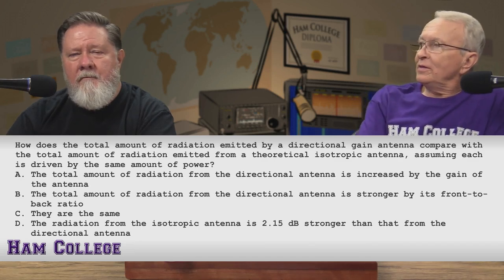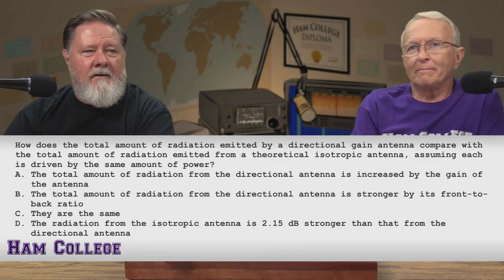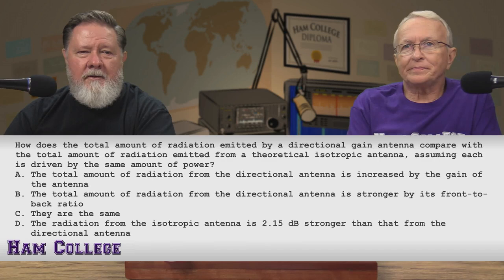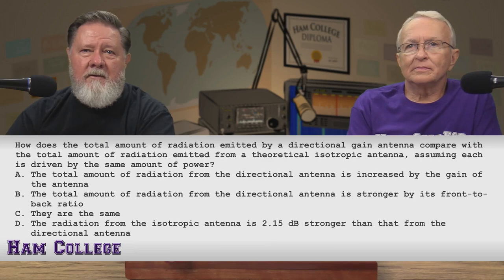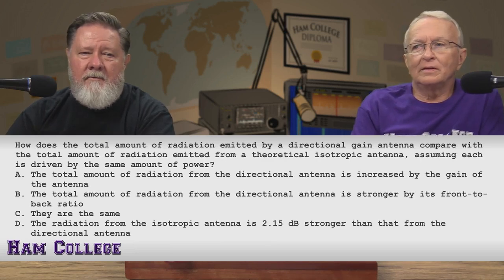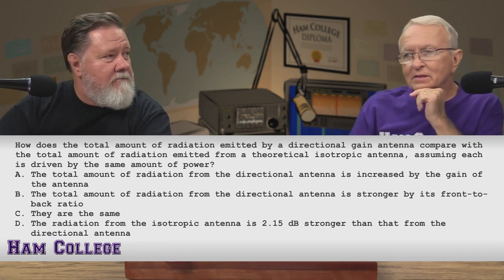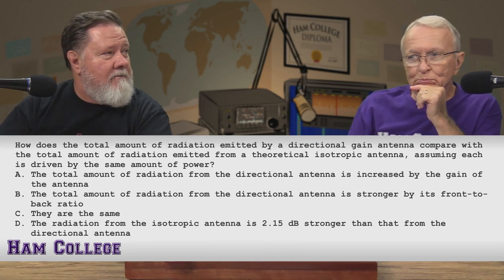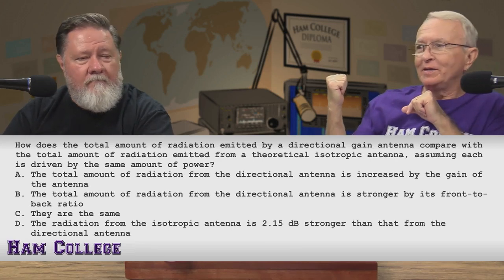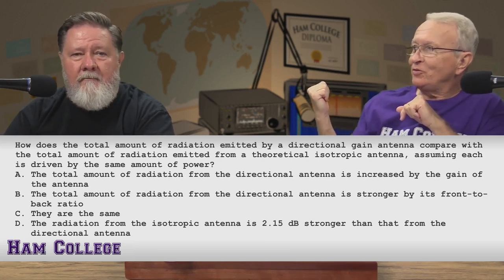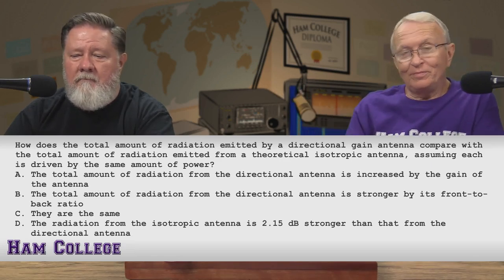Make sense to you? You're looking like it doesn't. Well, it does, but I was thinking about ERP and the gain of the antenna. I guess it's still the same amount of watts. But it acts like more watts. If you got 3 dB of gain, it acts like double in that direction. Over here, it acts like 3 dB less because you took away 3 dB here and you put it over there. Or roughly. So, yeah.